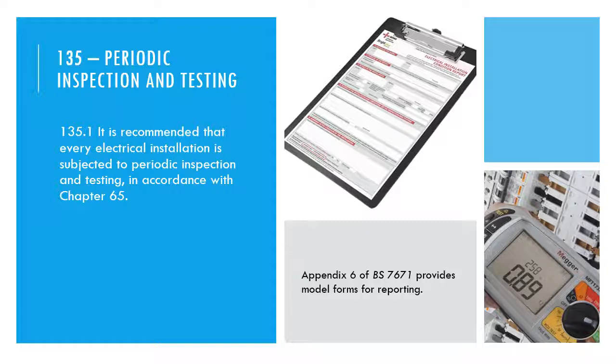We can see if there is any underlying degradation of the system and any potential maintenance that may need to take place. And we have in Appendix 6 model forms for writing down the answers and recording the results. All results and all information with regards to any testing and inspection of any electrical system should be maintained for the lifetime of that system.